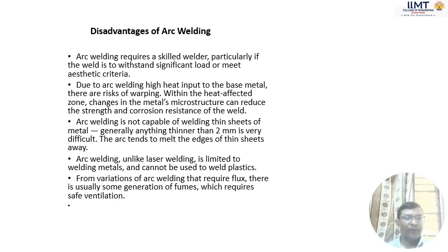Disadvantages of arc welding. Arc welding requires a skilled welder, particularly if the weld is to withstand significant load or meet aesthetic criteria. In this case, we generally need skilled welders. Due to arc welding's high heat input to the base metal, there is a risk of warping. Within the heat affected zone, changing the metal microstructure can reduce the strength and corrosion resistance of the weld. These are some disadvantages of arc welding.